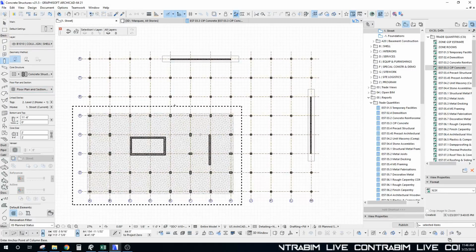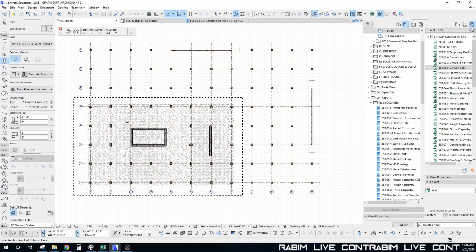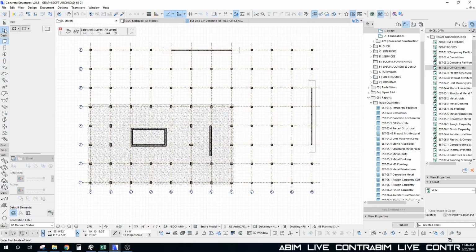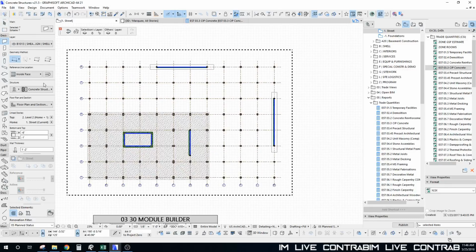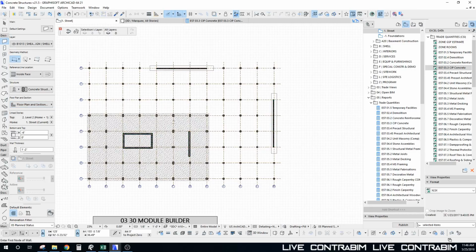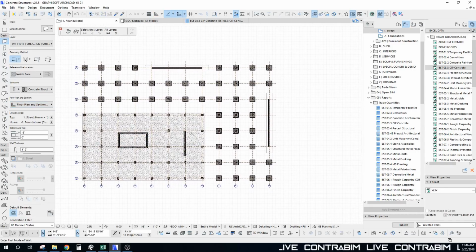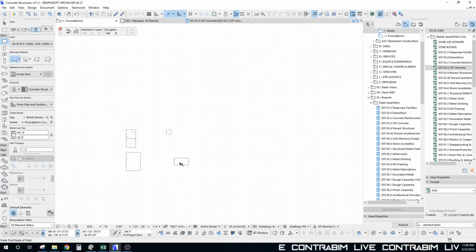And let's just change those because those were not showing up on our level below. So now they are. We need to do the same thing with our walls. So grab those walls and set them to all relevant. They were already set to -1 foot, but they weren't set to all relevant. That's why they weren't showing up.